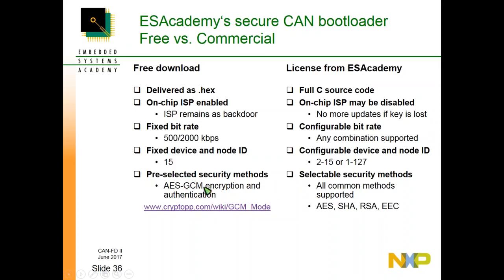In the source code we kept all the security modules completely separate, and we're not using any own implementation here. We simply use what's available. Some on the ARM embed web pages have several algorithms implemented, but once you have the C source code you could easily replace this with any combination of AES, SHA-256 we have already tried. We haven't tried our asymmetric versions yet because we think for our average customer this will be kind of an overkill, but the options are there.